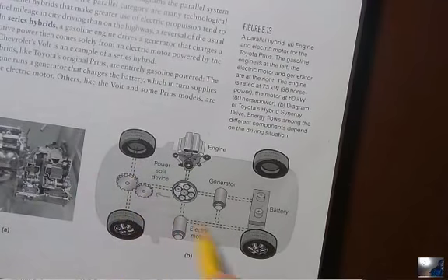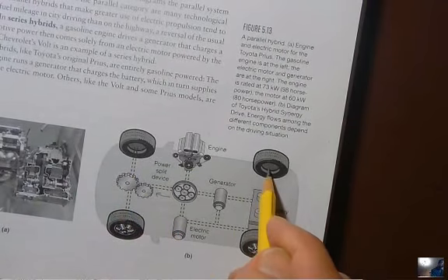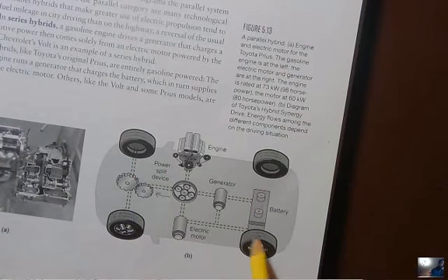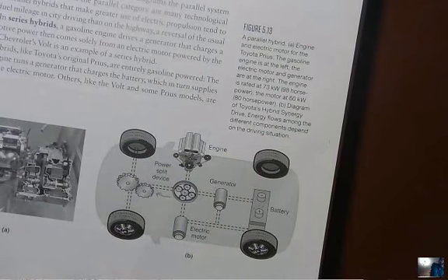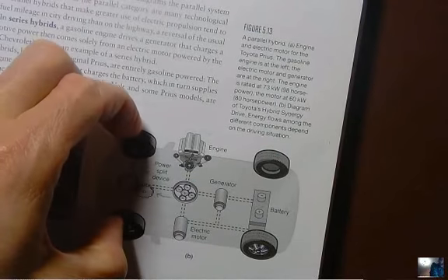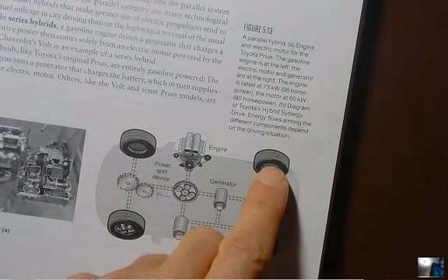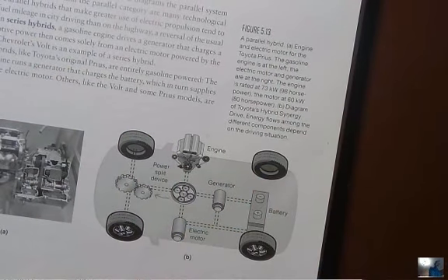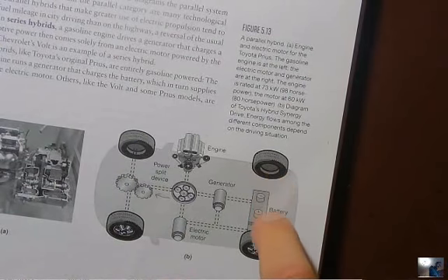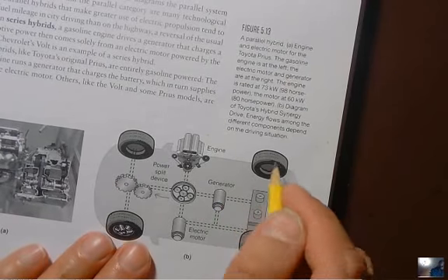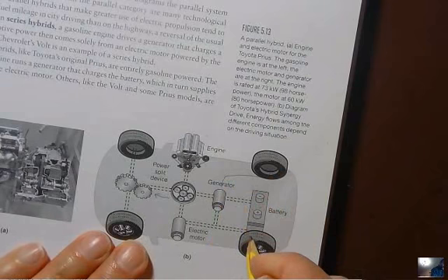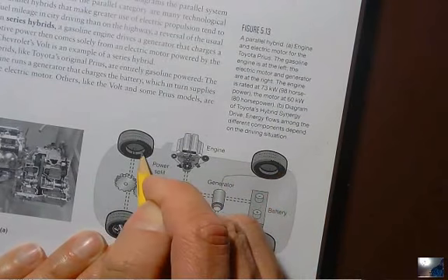The last thing that they're not showing on here again was this idea of regenerative braking, where there would be regenerative braking at all four wheels. When you press the brake, instead of something physical like a drum closing up to slow you down, it would attach a generator to the wheel, and that generator would just naturally extract the energy from the wheel and slow the car down, at the same time charging up the battery. So the regenerative part would come back to this generator here. Usually it's on all four wheels.